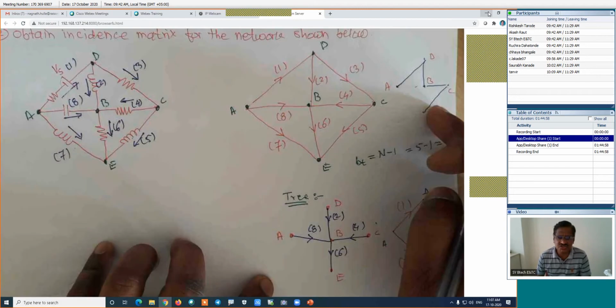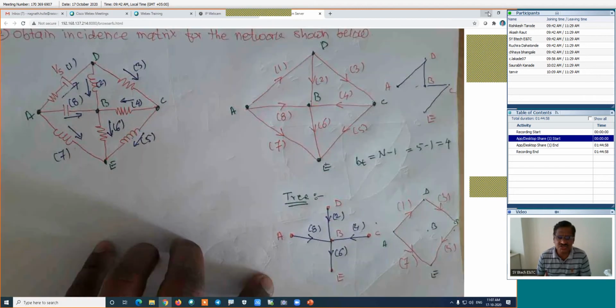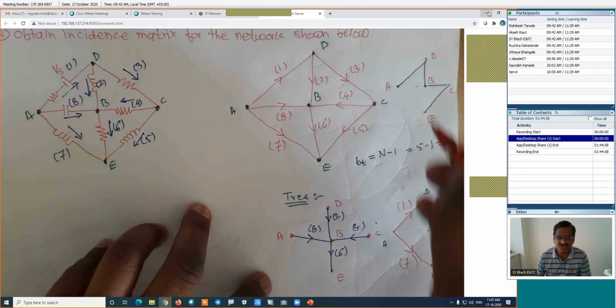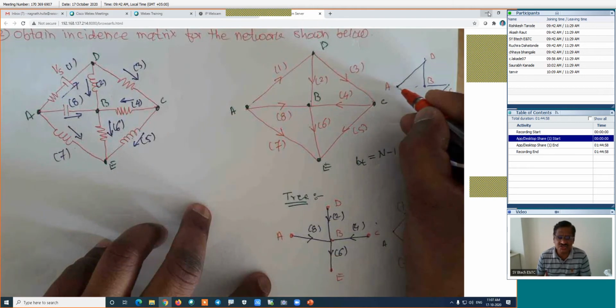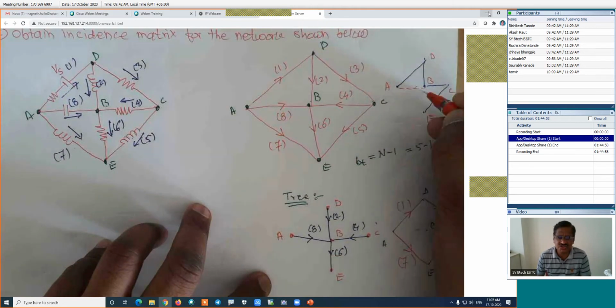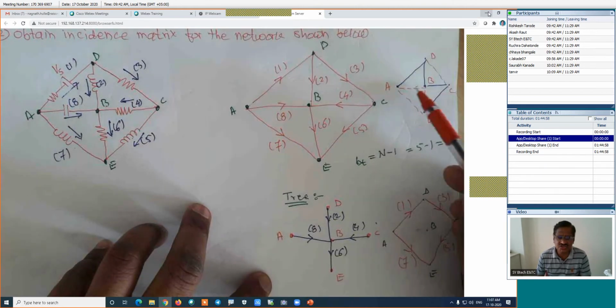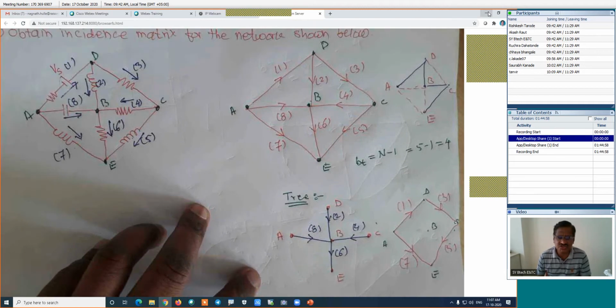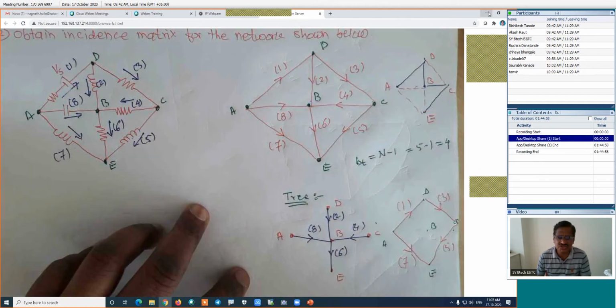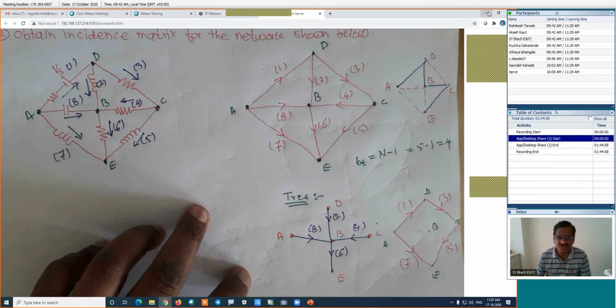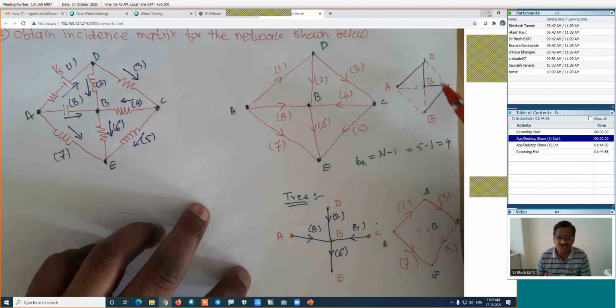And for this particular tree, there is again a code tree. How will its code tree be? I will draw it with the red lines. Here, this is one branch, second branch, this is the third branch, and this is the fourth branch, meaning nodes with 1, 2, 3, and 4 branches. Whatever I have shown by the red color and the dotted line, that is the code tree for this selected tree. We can show its orientations also.